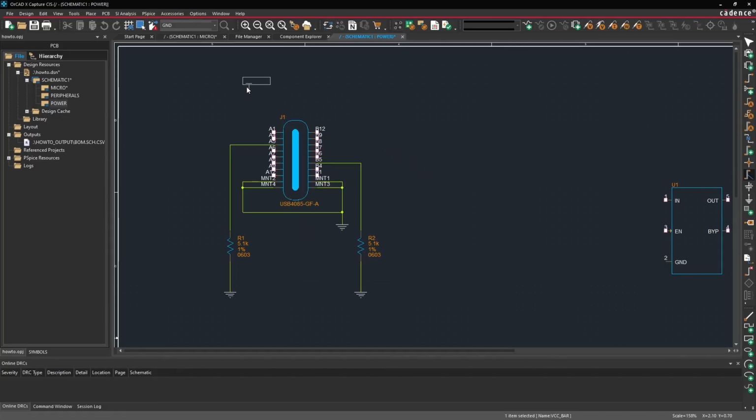It's just my personal preference, but you also have the VCC arrow, for example. I'm going to go ahead and place 2 of them. And we're going to connect A9 and A4 and B9 and B4. Now our net isn't actually called VCC bar.